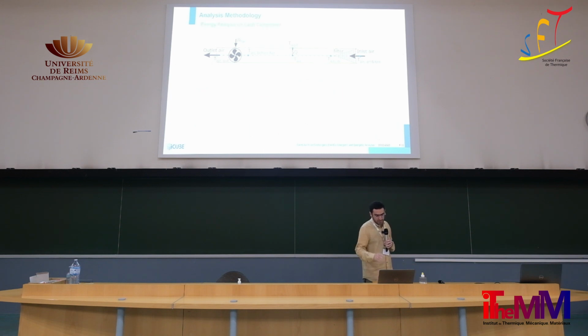So as we have seen, applying the exergy balance to the system permits us to find the exergy destroyed in the system. So now we apply this exergy balance to the different components of the system so that we can find the exergy destroyed in each component separately. Applying it to the filter, for example, can give us the exergy destroyed in the filter, and as so we do for the pipe only and for the fan, and we can then find the three destroyed exergies in each component.